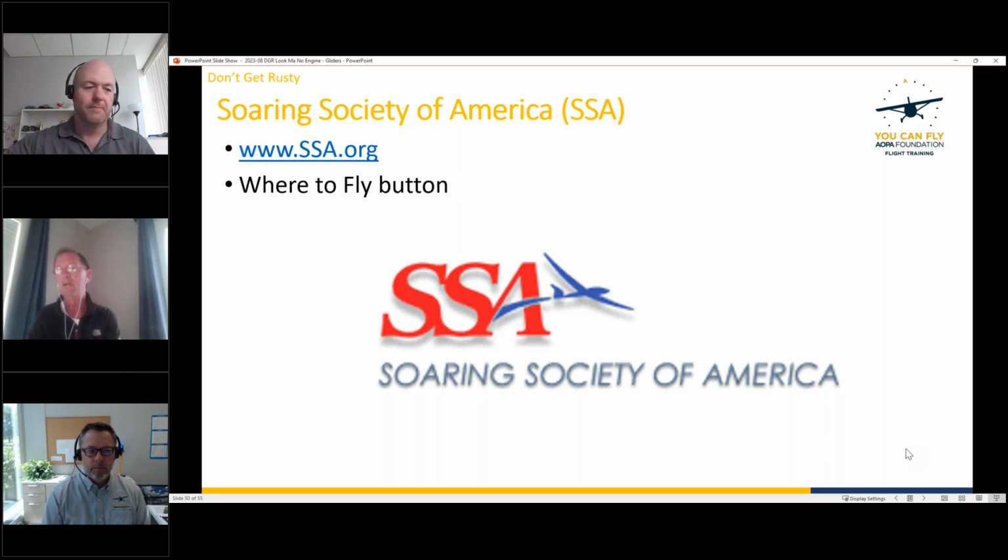Mm-hmm. After I got my glider category rating, I was working on getting my commercial in airplane so I could do the aerotow, and I was flying a Citabria. When I would come back into the traffic pattern, I would enter the downwind and pull it to idle and leave it there. I would fly the Citabria to the runway like it was a glider, and I was making accurate spot landings every time. I was reading an article recently where there's a guy who routinely, 5, 6, 7, 10 miles from the airport, will bring the aircraft to idle and make his way to the airport and enter the pattern and land, just to be in the constant practice of knowing what his performance is in various situations, evaluating the situation as it occurs, changing the situation as he needs to.